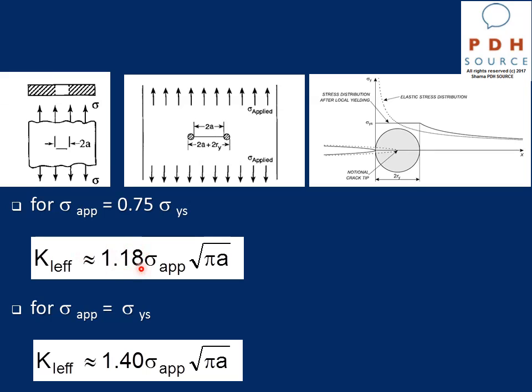As you see here, there is an 18% increase in the stress intensity factor. And even if we go very conservatively and assume that the applied stress is equal to the yield stress, we will get a 40% increase in this case.